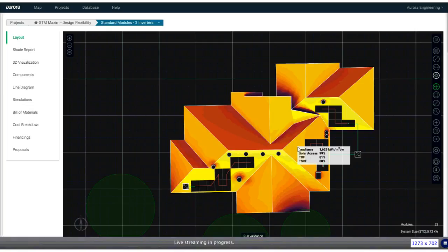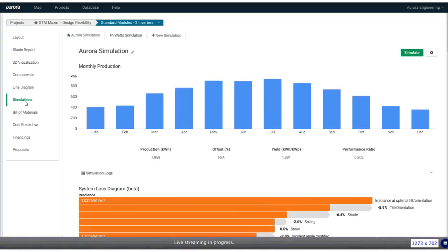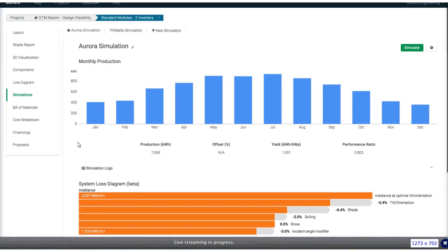Now, we did this because, as Daniel mentioned, if we were to string together these modules that receive different amounts of light, which we can clearly see from the irradiance map, the ones facing south are in a brighter zone there, we would have series mismatch, and we would likely just drag down the performance of the modules that are receiving more light. So we wouldn't really have an optimal design, and that's why it's not generally good design practice to string across multiple roof planes.